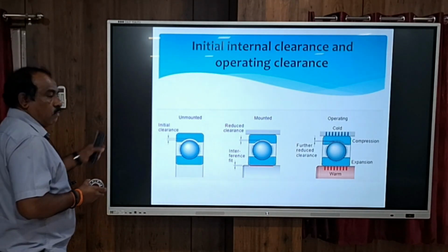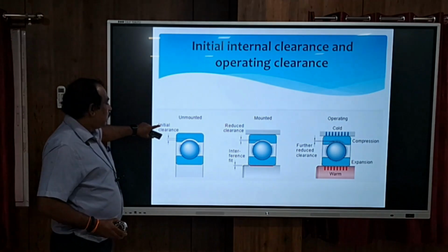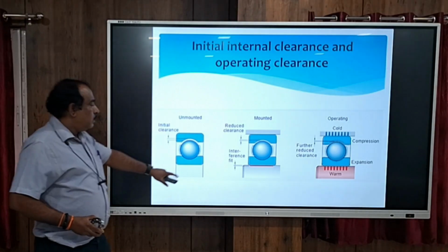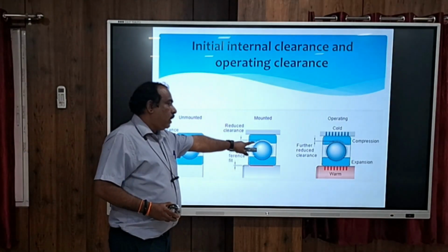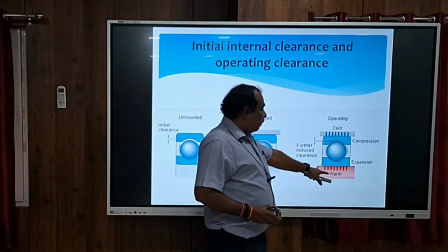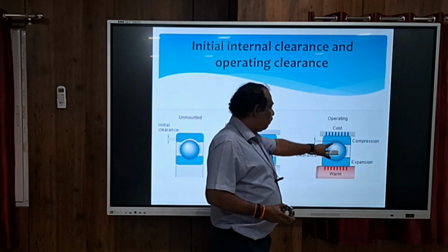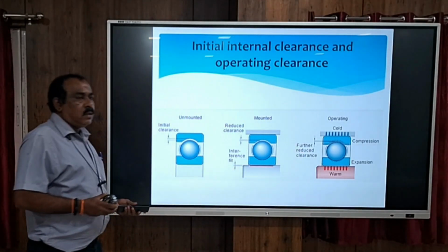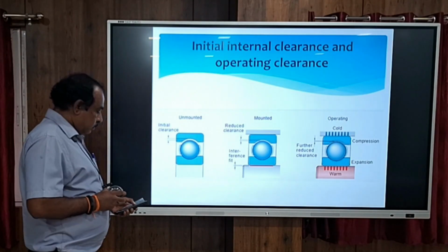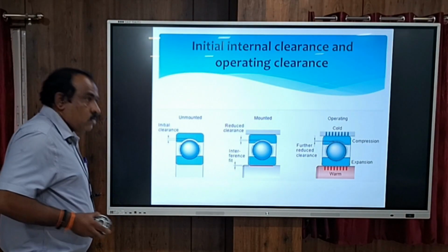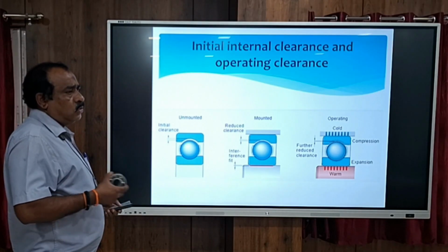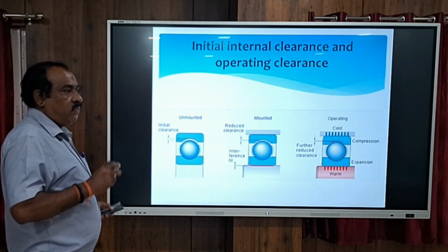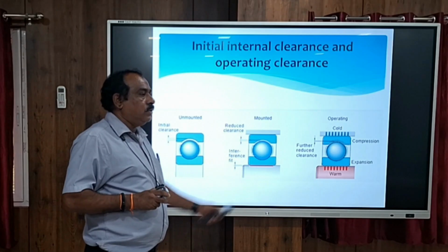And this is actually a figure explaining the point. This is the initial clearance, here more clearance is there, and then after fitting, the clearance will slightly reduce, and while running, the shaft temperature and all will warm to maximum. This temperature will still get compressed. So there, C3 clearance means it is on the safe side. The clearance is becoming less because the shaft will expand. The temperature will increase also when movement is there. Second, interference when we are fitting, after fitting only, and then this is during running condition.